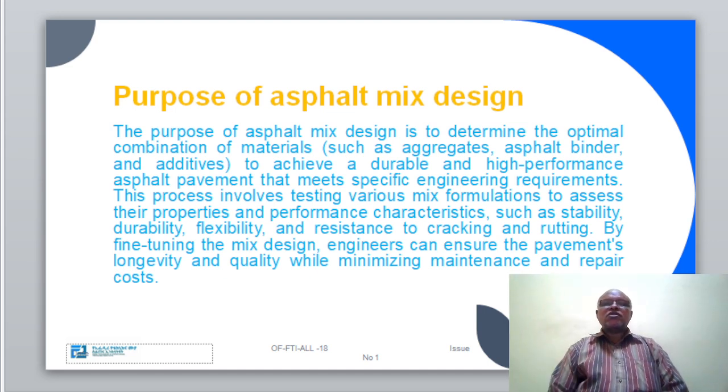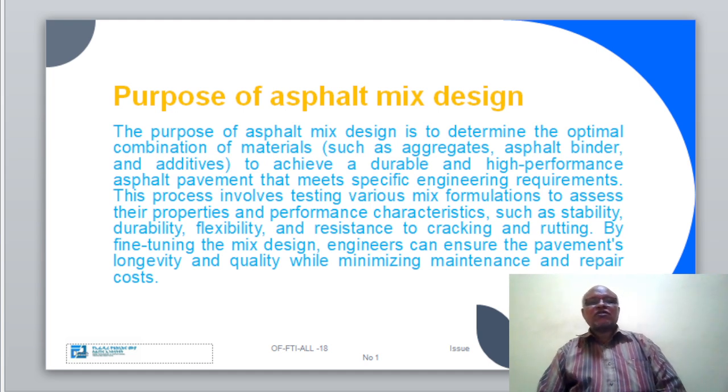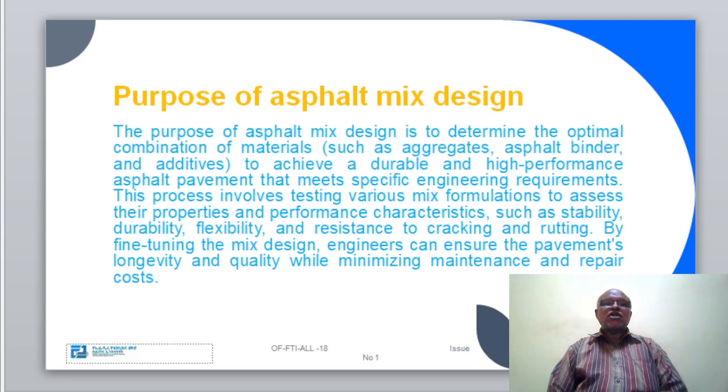Through rigorous testing and analysis, engineers can fine-tune the asphalt mix design to achieve the desired properties, such as rutting resistance, crack resistance, and overall performance. This ensures that the pavement can withstand heavy traffic loads and harsh weathering conditions for years to come.